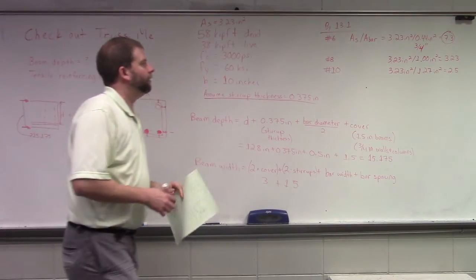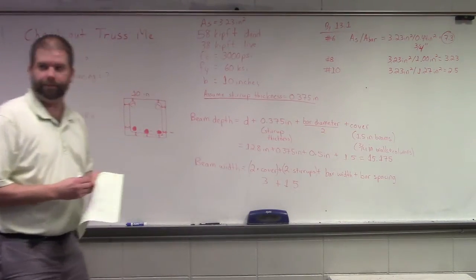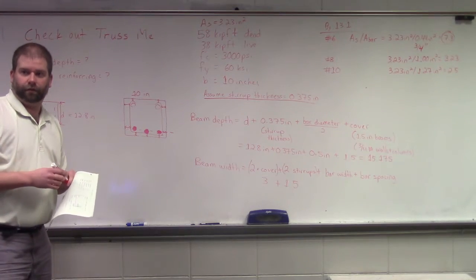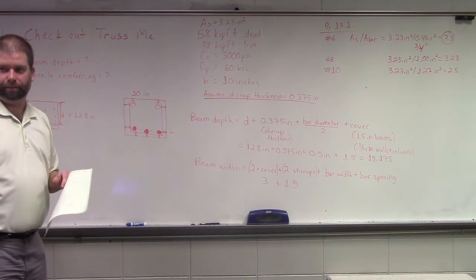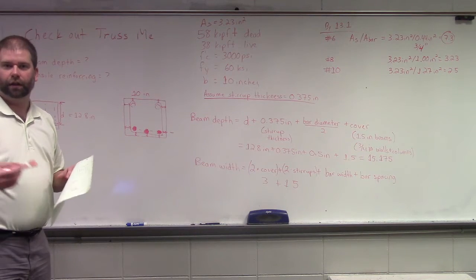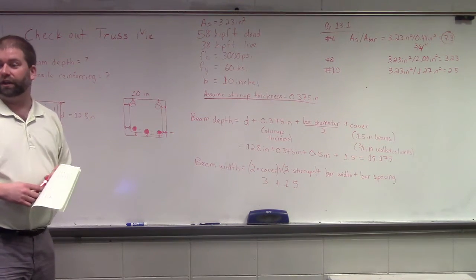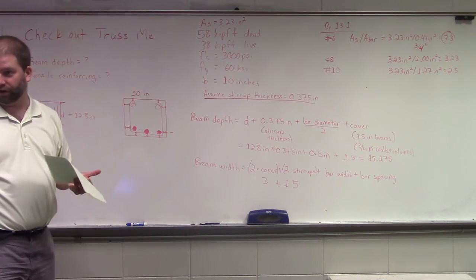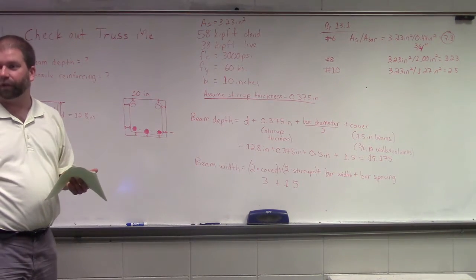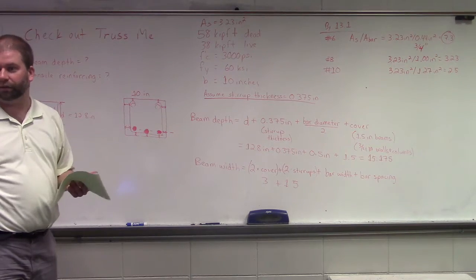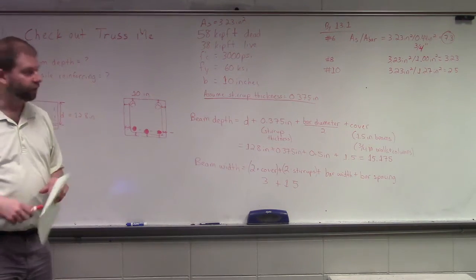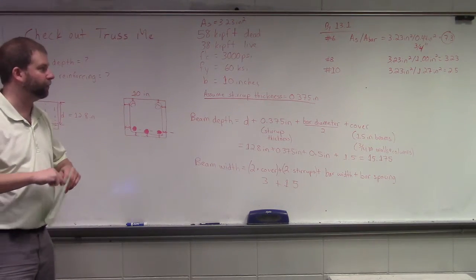When you look at 8, you need 4 1-inch bars. So we can't even put an inch. What if you put a 1/2 inch in between them? If we're going to put a 1/2 inch in between them, we have to place a mortar. We can't place concrete, because of the aggregate. We're not going to be able to get 3/8 inch aggregate through that. So that's where the problem comes in.